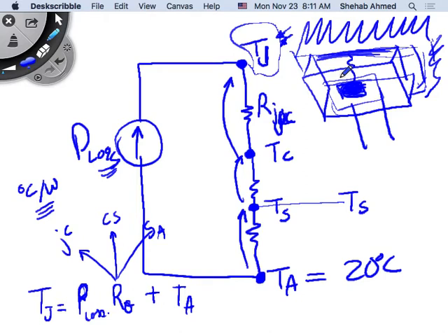Because if the case has a metal pad in the back, the metal pad is actually a live electrical terminal. So you cannot just put grease. If it's a completely plastic, insulating case, yes, you can just lay it on the heatsink. No problem. A heatsink is metal. You can put it there, and it will dissipate the heat. But there are some cases that have a metal pad in the back. These metal pads are electrically conducting. They're actually connected to one of the electrical terminals. So you cannot just put it on a heatsink.